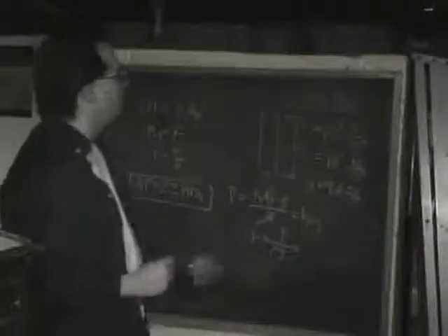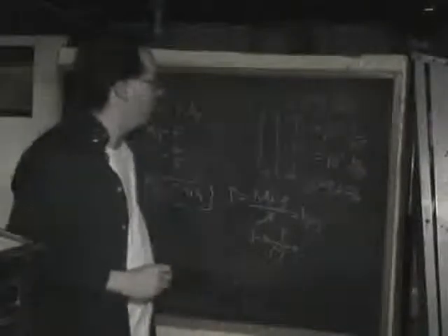Height, so pressure, and actually we want the height, we know what the pressure is, we want the height in terms of the pressure. So we want height, H, is going to be equal to pressure, P, over rho times G. Well, what's rho times G? It's going to be 10 to the third kilograms per cubic meter times 10, roughly, meters per second squared.